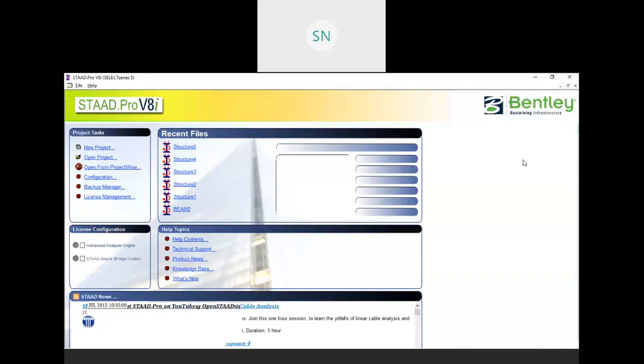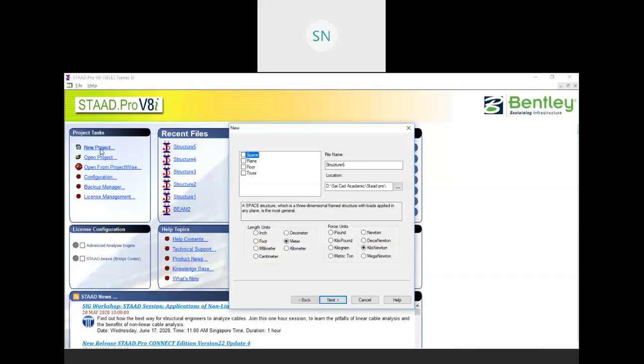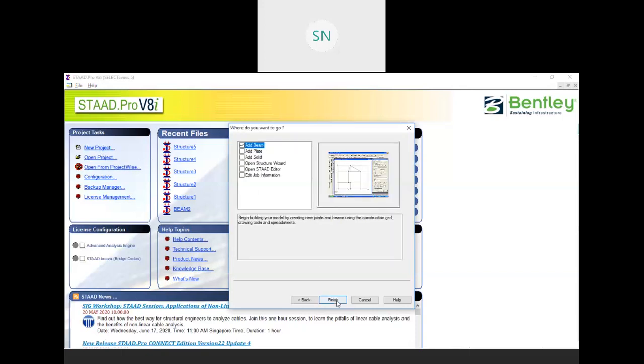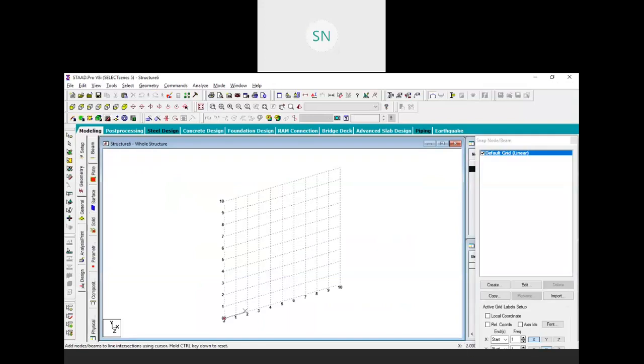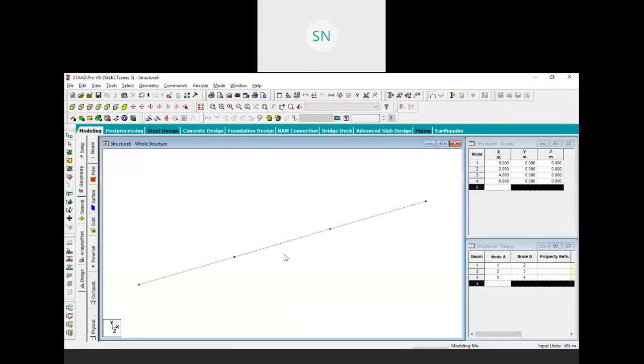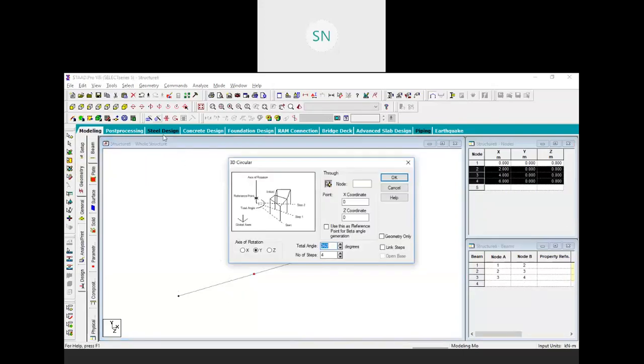So see, now focus over here, okay? And first of all, I have created three beams over here at 2 meter spacing. So these are the three beams. Then I want to create a water tank floor first. So we need 4 points to create plates. So I select these 3 points and go with the circular pattern. I just want one copy at 20 degree. So we are using a 20 degree interval.